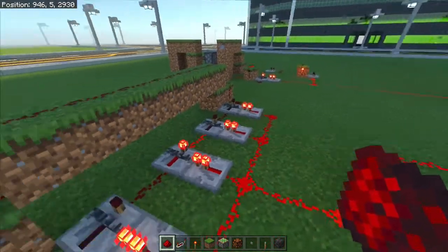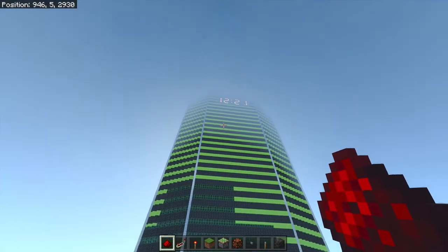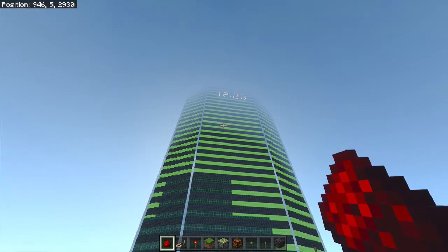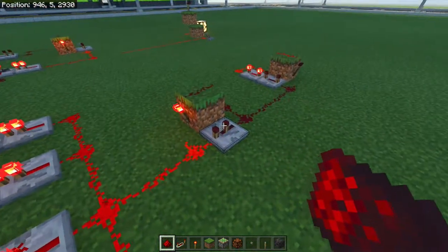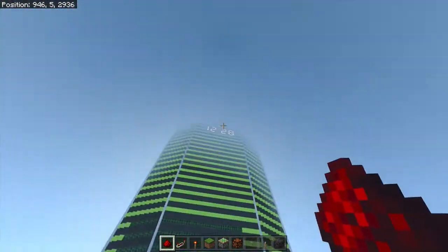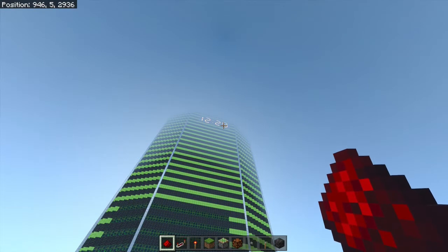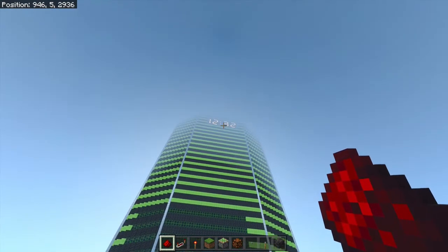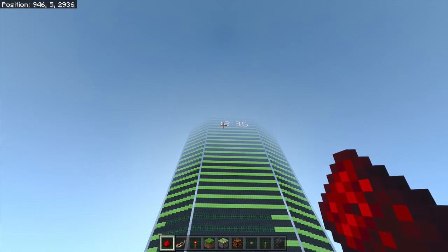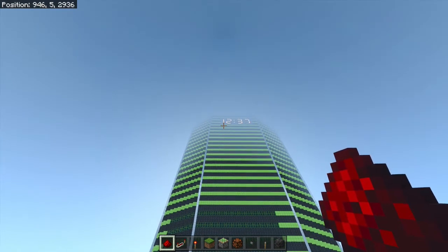Now, exactly the same thing is happening here as is going on behind that clock. We just have 3 of those state machines. The one on the right side ticks every second-ish. It's actually exactly like this one where it's an 18-tick cycle. And there's 10 states, from 0 to 9. The second one has 6 states from 0 to 5. And then the third one controls the first 2 digits, and it has 12 states.